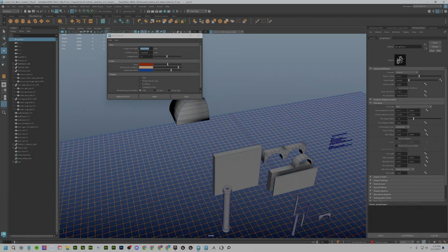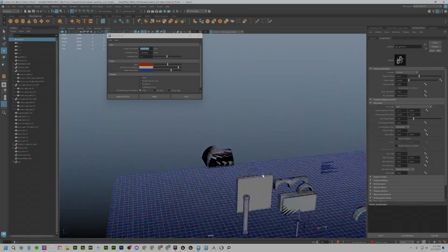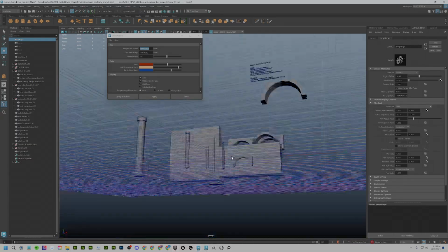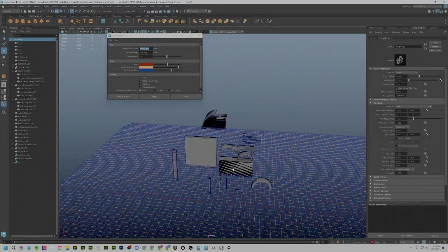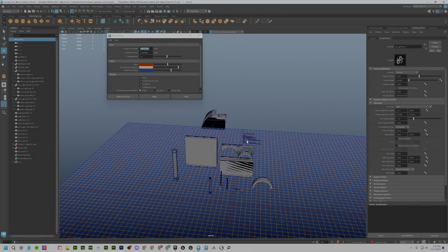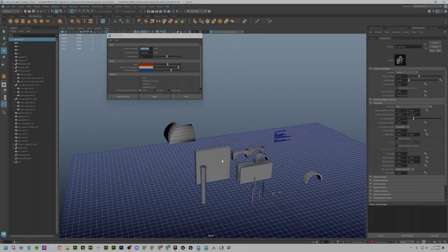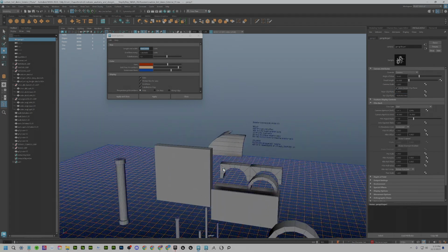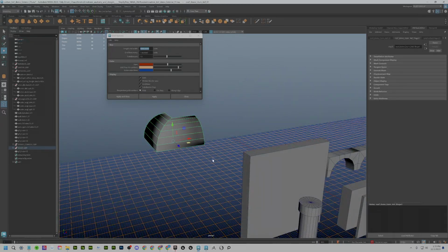But the other problem is the near clip plane, which is even more annoying in some ways, and that is you're getting this really harsh, almost like Z-fighting flicker as soon as you get to a larger scale. For some reason, I never knew this before, but if you actually increase the near clip plane to a value of about 3 or 4, it gets rid of that annoying clipping artifact. So I just accepted it as a bug in Maya all these years and just discovered that recently.